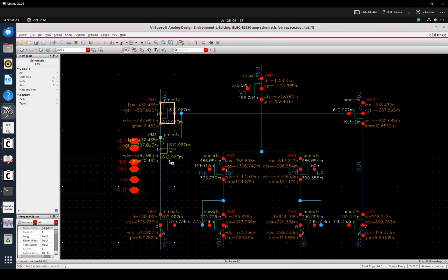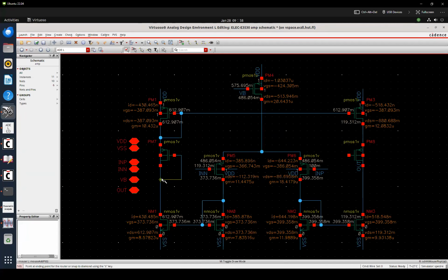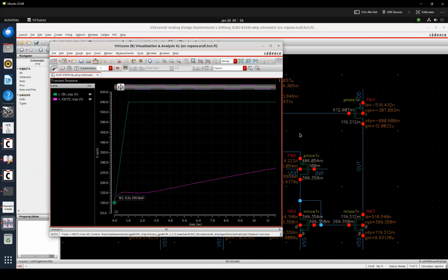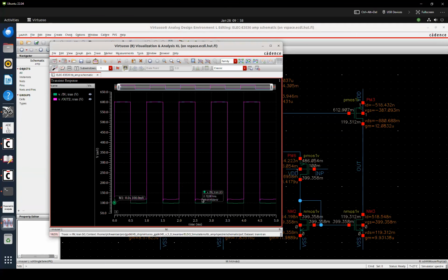Okay, so when you set cascade configuration like this, then its drain mismatch is reduced. Your current metering mismatch is reduced, and the current meter accuracy is improved. In this case, you can improve the transient simulation accuracy. But for this kind of very simple circuit, there is no way around to further reduce this mismatch as good as this high voltage. What happens for the 600 millivolt?